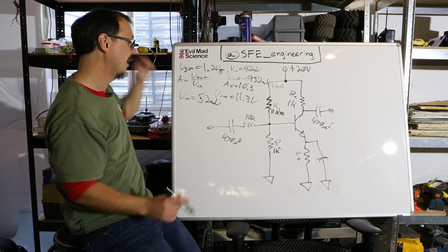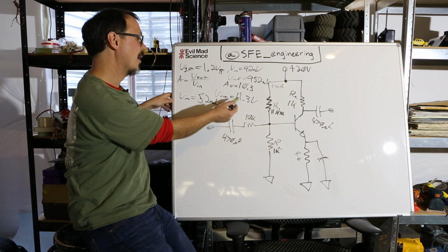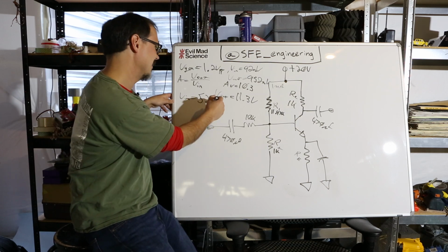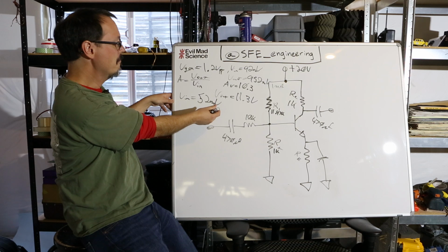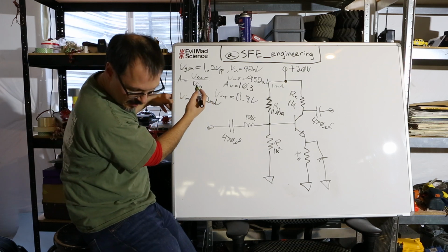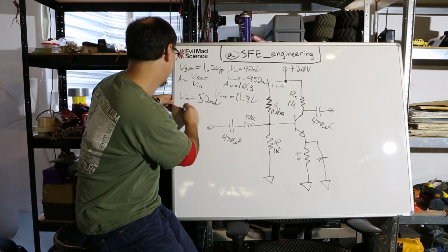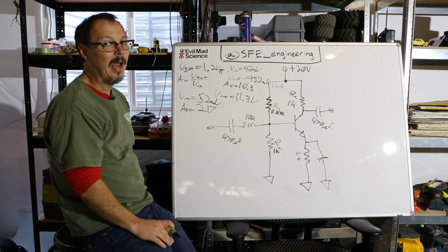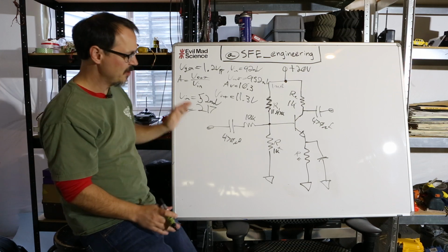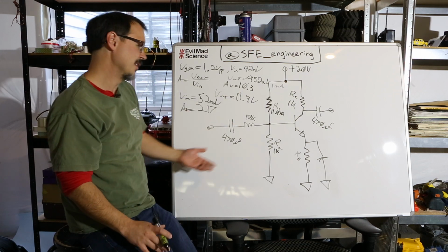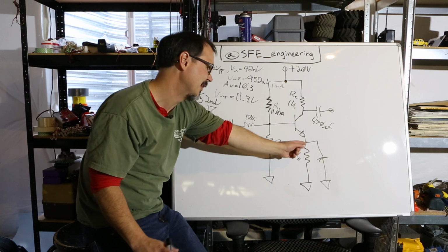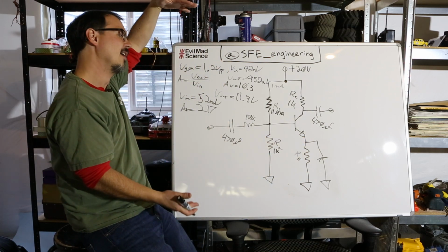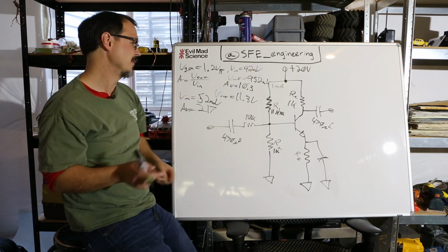input impedance, okay? But also, 11.3 volts divided by 52 millivolts, sorry, that's a V. 11.3 divided by 52 millivolts, and that gives us a gain of AV equals 217. Holy cow! So that's a lot of gain. But as you see, your input impedance goes down. Another plus is you get that extra volt back because you're not operating in DC land for your AC signal. So you get the full swing of VCC to ground. So that's kind of cool too.